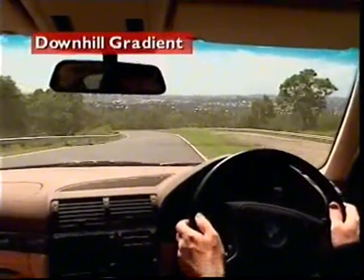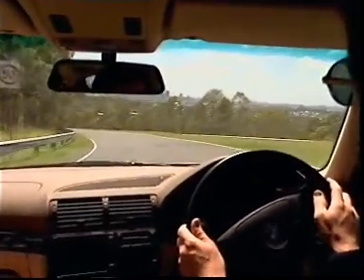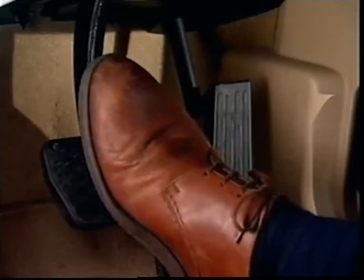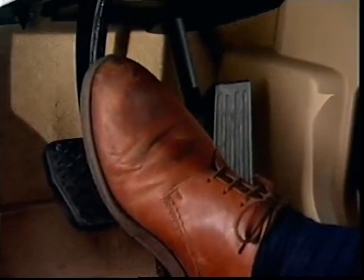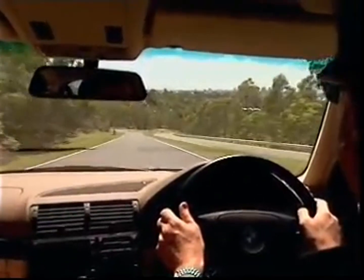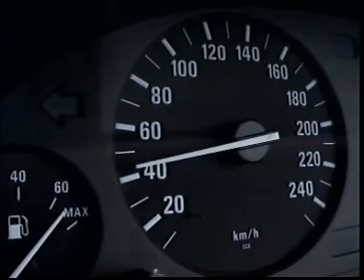On a downhill gradient, if an upshift occurs when the accelerator is released, there is no engine braking. To stop, the driver would need to apply greater force to the brakes. And vehicle road speed tends to increase even if the accelerator is not touched.